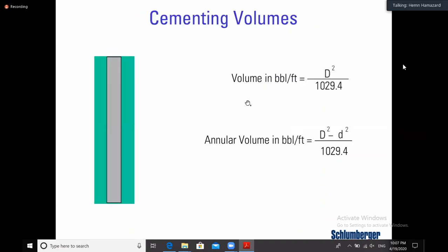And of course, as a drilling engineer or even well site drilling engineer, even the drilling supervisor's job is to calculate how much cement you want. Any volume or capacity has been simplified in the field. In the plan, you need to know how much cement you need, how many meters in the annulus. For example, you need 200 meters. The first thing you calculate is how many barrels you need for 1 meter, and then you multiply by 200 meters. You say I need this much cement.